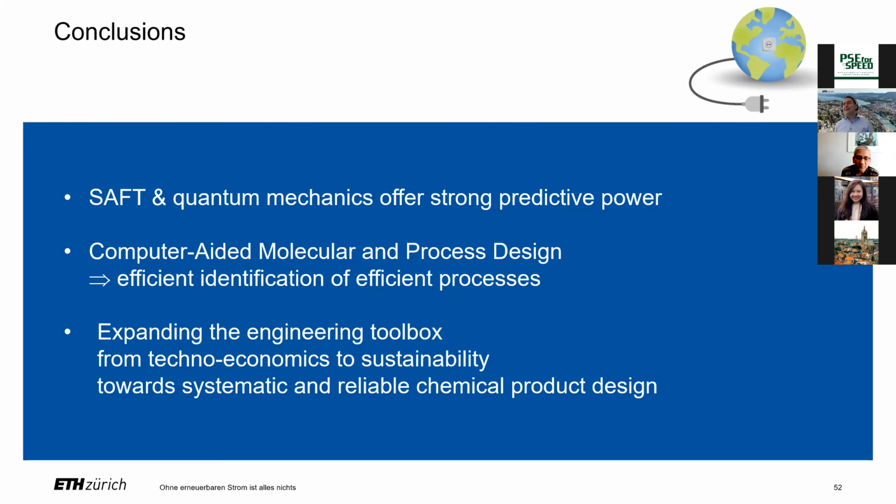So the organic Rankine cycle by itself, you can use it only to generate power, and I need to reject heat at the lower temperature level. Sorry, I was reading the question just now. I misunderstood. But you can apply the same philosophy to heat pumps to produce cooling power. There is a lot of activity at the moment in heat pumps to integrate them into systems, and that's very exciting. But the organic Rankine cycle needs a higher temperature heat source and rejects at the cooler side. Sorry about the confusion.